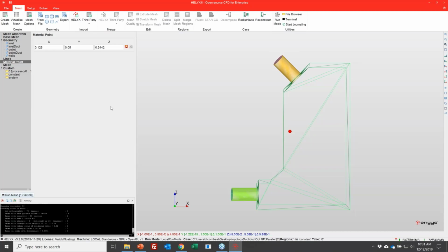So for example, with layers, this is one of the reasons why other open source meshers might have a lot of layer collapse. So it's a quality driven mesher, and these metrics are determined based on experience with the solvers. And I'd say 98% of the time, we don't adjust these quality metrics.